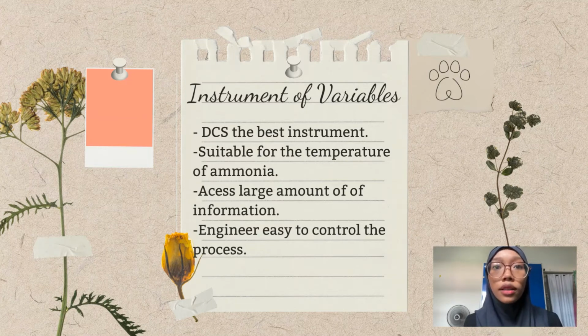These field devices or smart instruments are capable of communication with PLCs or other controllers while interacting with real-world parameters like temperature, pressure, etc. The temperature of ammonia to keep liquid is negative 33.33 degrees Celsius. So, DCS will keep monitoring the temperature of ammonia. DCS also accesses a large amount of current information from the data highway and monitors trends of past process conditions.